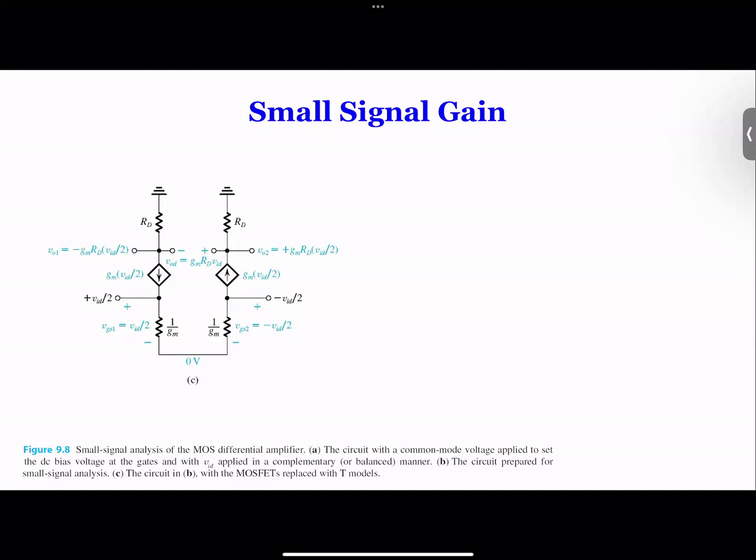So, and if you look at here, why this T model is more beautiful? Because you simply have this one loop. The current, it's just one loop. There's no branch, nothing. And the current over the whole circuit is exactly the same. Current flowing. And because the current flowing the same, you can easily calculate how much voltage is at the input side and how much output is at output side. So output divided by input, you got the gain. So that's why in the book it always says by observation. By looking at the input resistance, output resistance, we actually got like the gain.